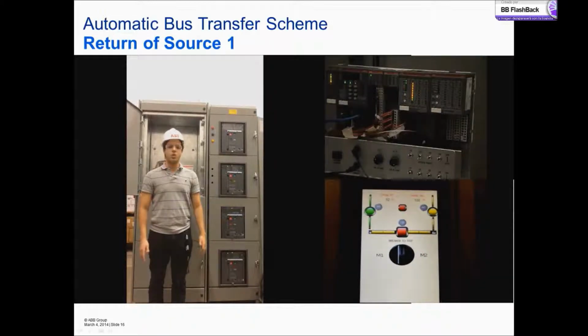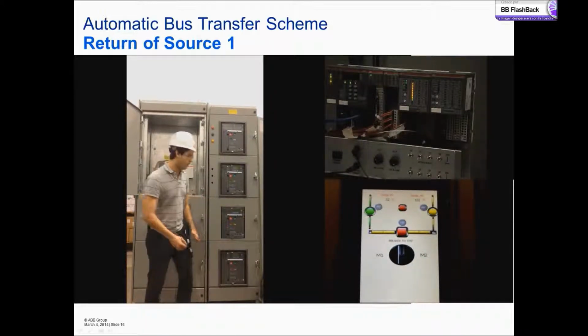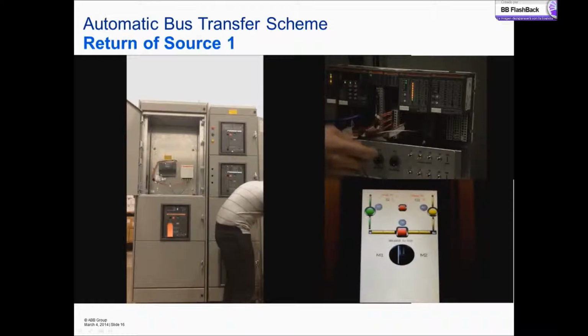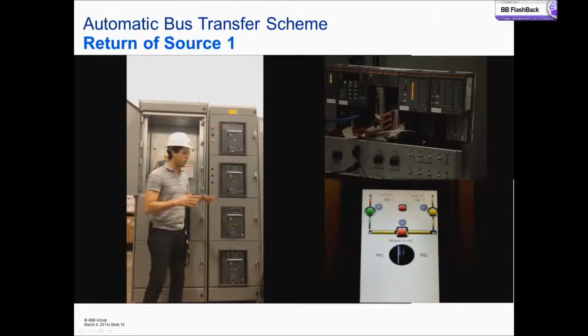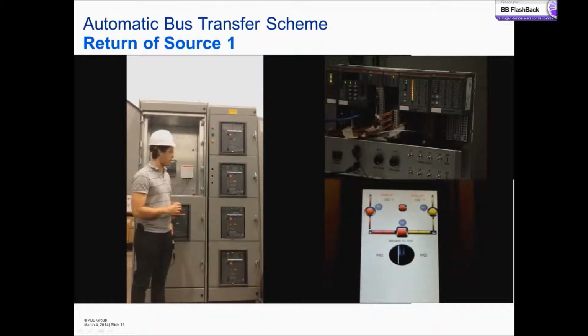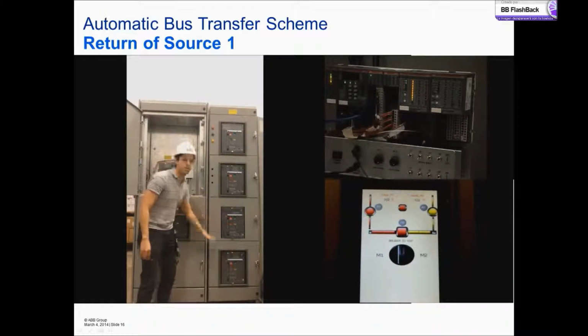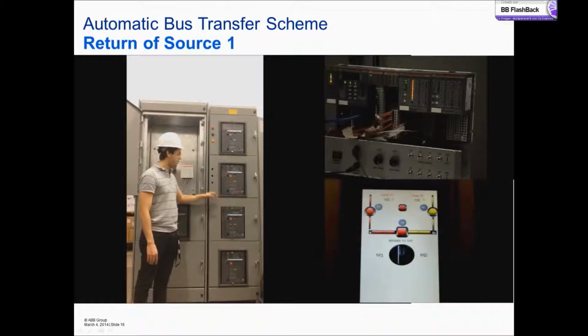In our case 2, the voltage returned. So with the same step with the analog input, we return our voltage. The PLC remains 10 seconds waiting for the command, and there you go. We have parallelism between the 3 main breakers, and this one will open after 10 seconds.